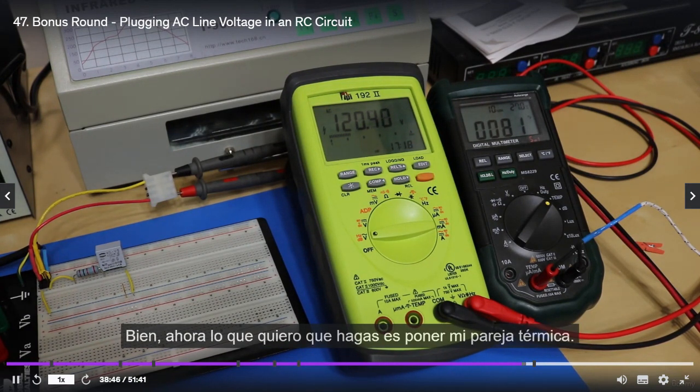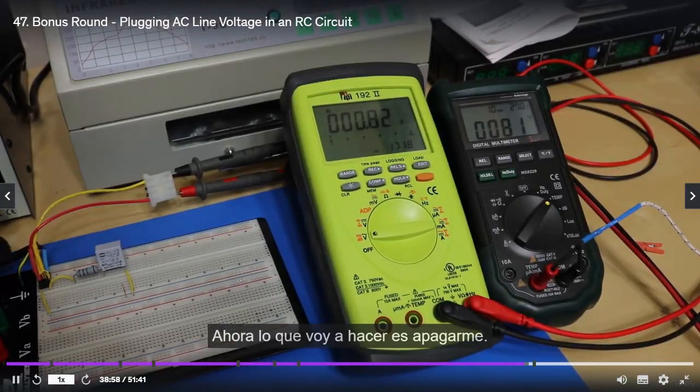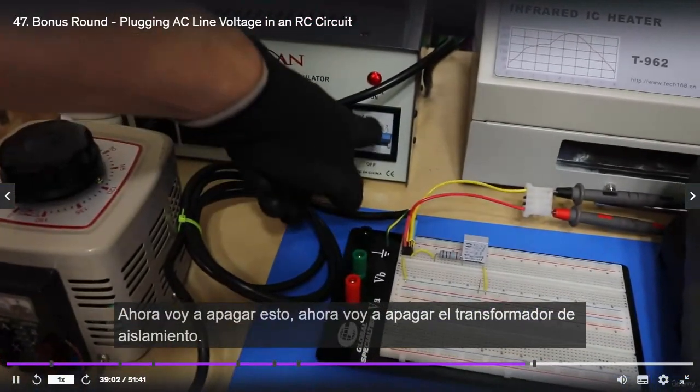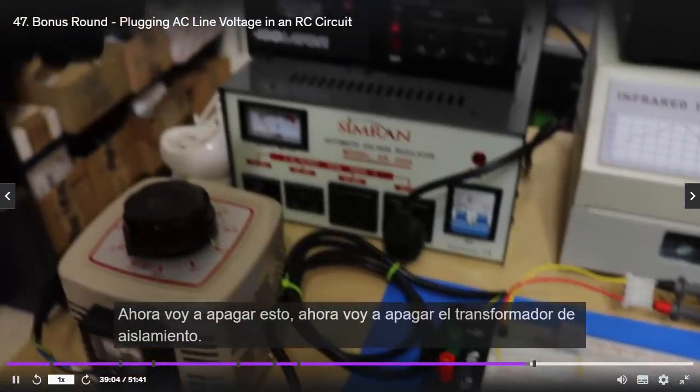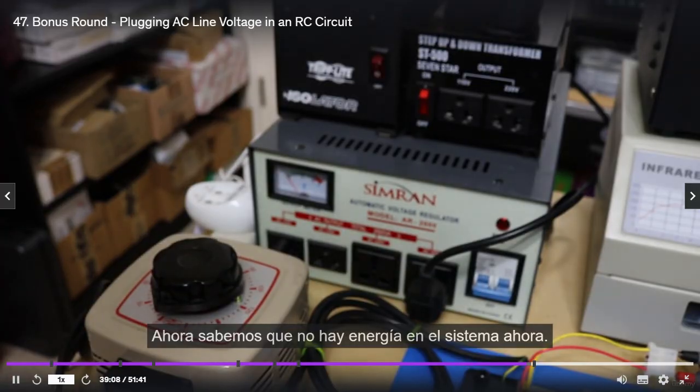Now I'm going to put our thermocouple on. I'm not going to touch this while it's hot. I'm going to slowly run down the power, so I'm running down the Variac. Now I'm going to turn things off, and you do it in opposite order. The Variac is turned off. Now I'm going to turn this off. Now I'm going to turn off the isolation transformer. All right, now we know there's no power in the system.